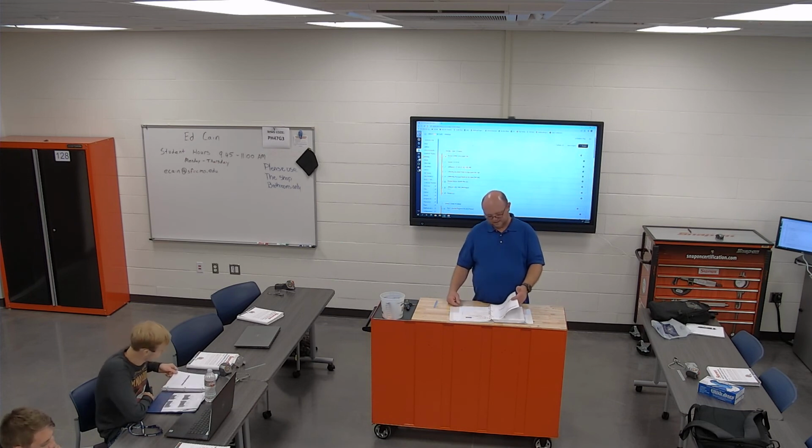There you go. See where it says aluminum? Greater than 1 inch, because that's our cutter's greater than 1 inch. On the lathe, it's the other way. It's the size of your saw. So it says 7 thousandths. So you would put RPM times that 7 thousandths times the number of flutes.